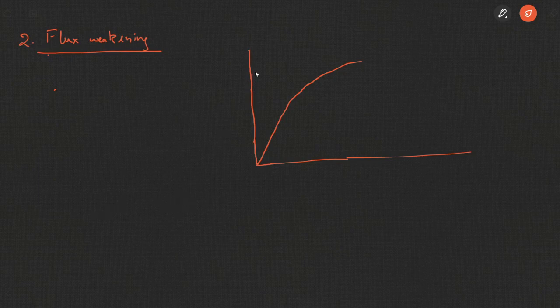What we have seen is that because of the increase in flux phi I, and if this was the average flux earlier, phi d will be more predominant as compared to phi I, because the machines tend to operate in the saturation region. So the increase in flux is no longer as much possible for the machine. The increase in flux is not as much possible as the decrease in flux is.